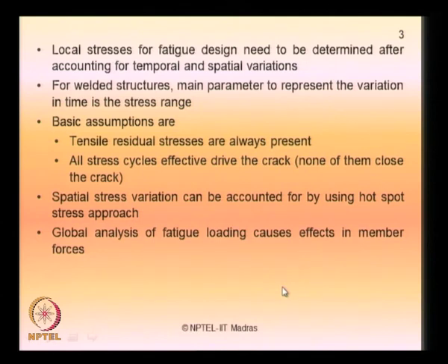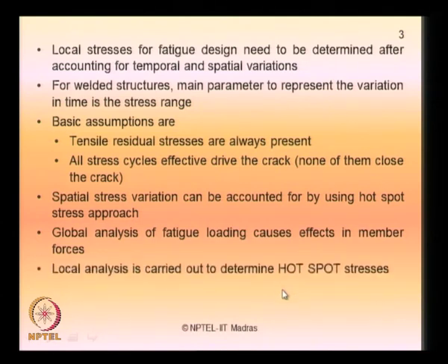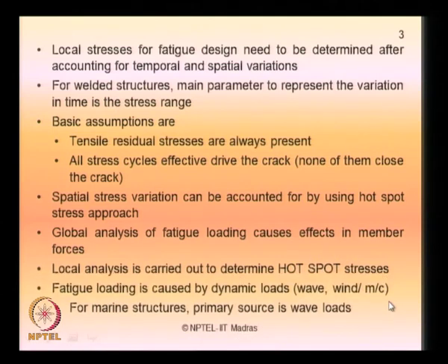Global analysis of fatigue loading gives effects in member forces, whereas the local analysis is carried out to determine the hotspot stresses. There are two kinds of analysis we carry out for members under fatigue loading. One is the global analysis, which gives the members' forces, whereas the local analysis is focused on hotspot stresses occurring at the stress evaluation plane, as we saw in this figure.